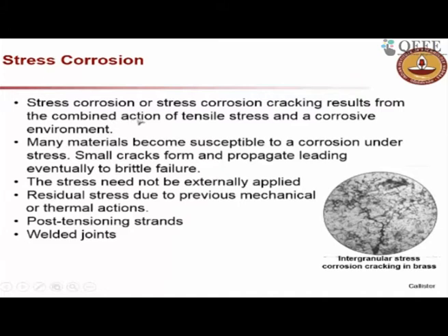It results from the combined action of both tensile stress and an aggressive or corrosive environment. So with both stress and a corrosive environment, the rate of reaction may be much higher and the metal much more vulnerable than in a case where there is only a corrosive environment and the metal is not experiencing any pre-stress.